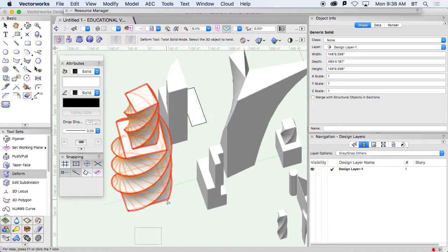What's that one that you made, like the hollow water slide thing? Is that the slide? With the sweep? Oh yeah, the hollow water slide, maybe it was a sweep tool. Yeah, so the sweep tool, again, if you're doing multiple rotations, it asks for your sweep angle. So you're going to put in either 360, it's going to go one rotation, or I did times 8 and it did a screw, right? Okay. I love it. The sweep tool, I forgot what that was called. Yeah, so that's the sweep tool.